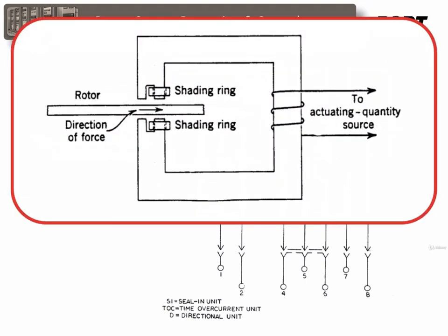This relay uses old school trickery, which I won't go into right now, controlling the enhancement or the restraint of the operating coil of the timed overcurrent unit by switching it in and out, or by switching in and out shaded poles acting on electromagnets of the disk movement.